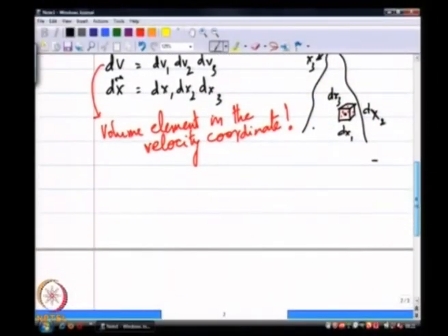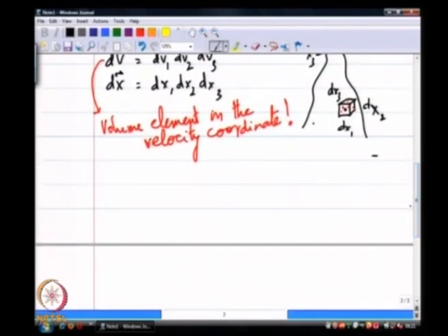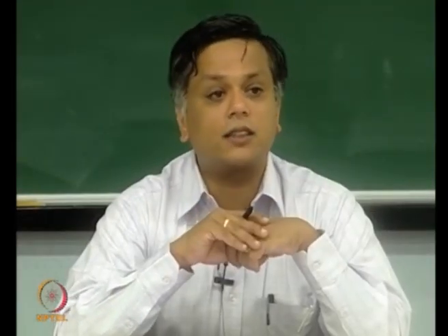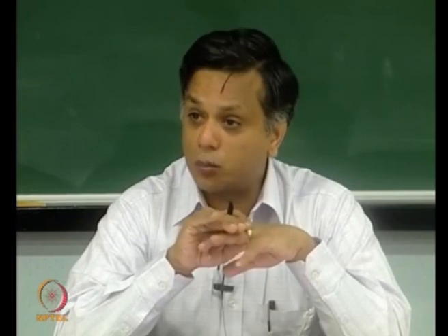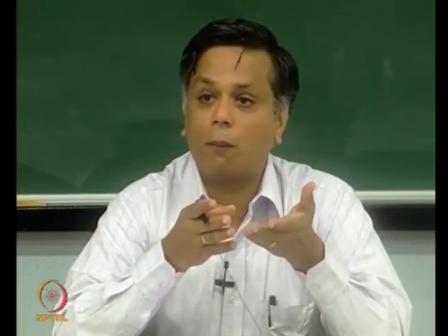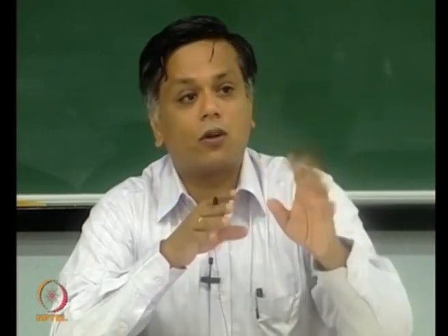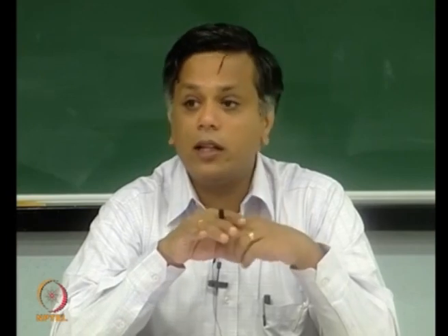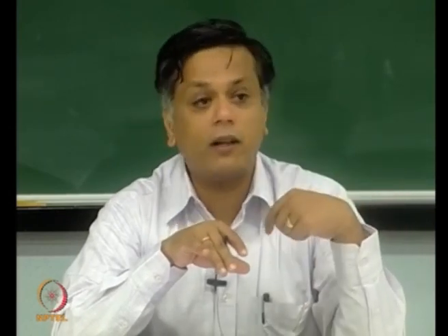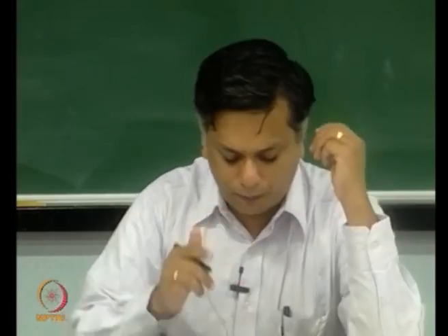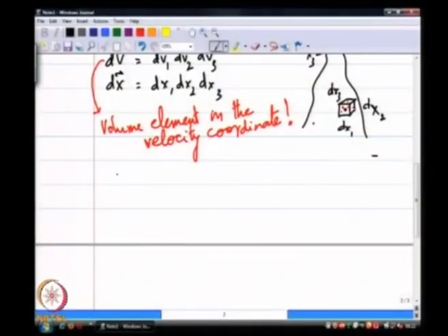So, now we want to write an equation that describes the evolution of f in space, time and the velocity coordinate. So, the velocity is now an independent coordinate, just like space. We are not going to make any distinction between velocity and space. It is like at this point I have a certain drop at this location moving at this velocity. This position and velocity are both characteristics of that drop, they are independent variables. There could be other dependent variables that fall out of this, we will look at those. Okay. So, now let us go back to this idea of a simple co-moving derivative.